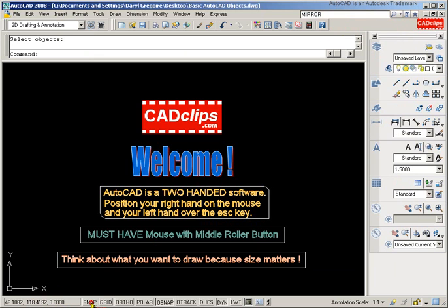Okay, down over here we have snap. These are toggles using snap, grid, ortho, polar. We're going to learn about all of these. You can see your units are down inside of here. Anytime you're kind of caught in something, just hit escape a couple times on your keyboard to get you out of that. As you move your mouse around, you'll notice these units are changing. The 0 isn't because that's the Z. This is the X, this is the Y, and this is the Z. And it's just the coordinates of where your mouse happens to be at the time. We'll talk a little bit more. If you change this to be feet and inches, it will give you feet and inches. Right now it's just giving you decimal units.